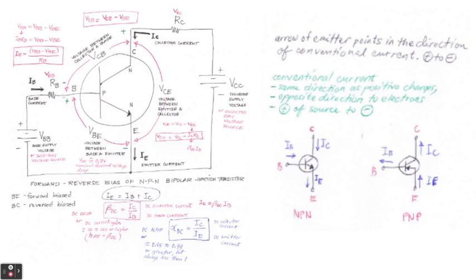This is very important to know. This will be the basic calculation for the current on the base: IB is equal to VBB minus VBE over RB. Now, in the case of VCB or VBC, we can calculate it by subtracting VCE minus VBE, or you can say VB minus VC also, if you want to calculate for VBC or VCB.